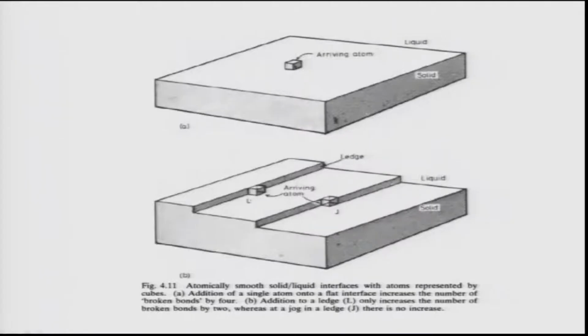But here it is in touch with the bottom and one of the sides, correct? Now a better situation will be to create a kink, okay, as you see here there is a kink. A kink is nothing but like this, you can create a kink, and this kink, shown as a Z, can allow the atom to satisfy its 3 bonds. So if I create many such kinks, I can allow many atoms to come and jump and attach to the surface of the solid.